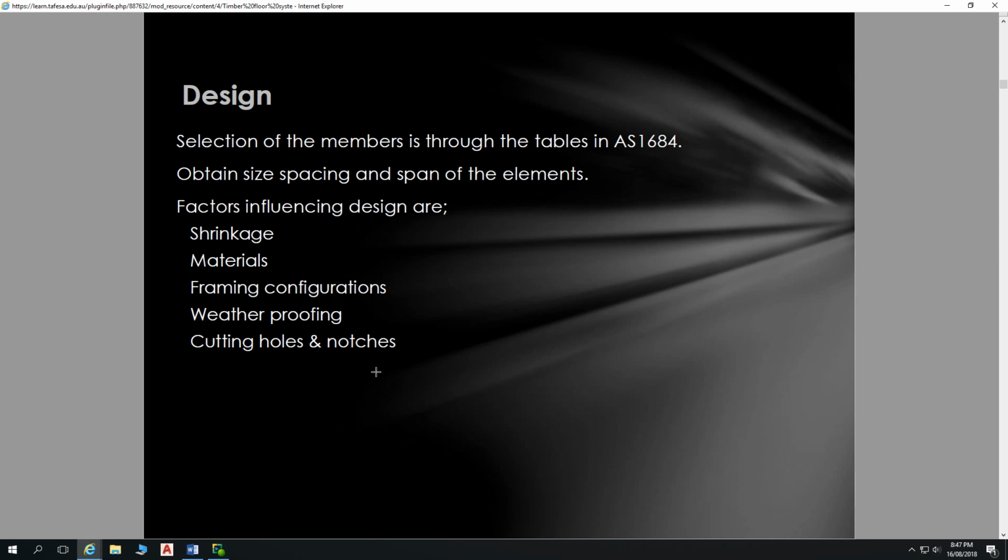So the reason for that is, we put a load on here. The bottom of this piece of timber becomes under tension as it wants to bow down. This bit gets stretched. This bit is under compression. It gets compressed as it's trying to do that. Our compression is the most right at the top. Our tension is the most right at the bottom. As we go through, those forces become less and less and less till we get to the center of the beam where there's basically no compression and no tension.